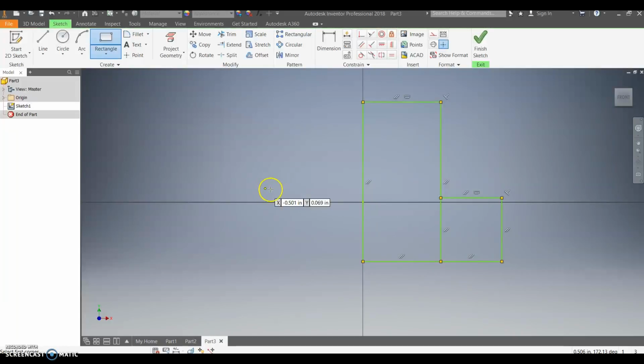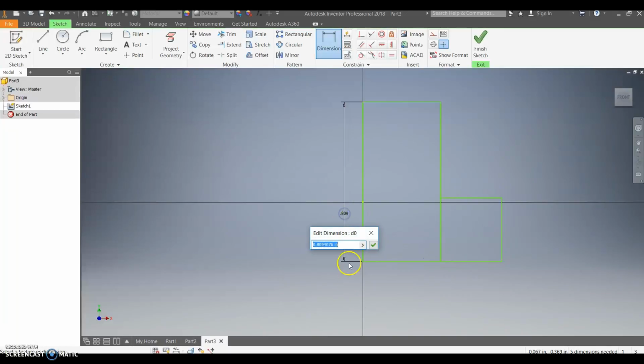One thing I'm going to do first, though, is I know that these are two different drawings. And if I add dimensions, like this, and I want to go and trim this later, alright, I can do so. This dimension's not right, obviously. So we're going to change this. The trim tool was highlighted. When a tool is highlighted, I cannot click on a dimension line. I actually have to hit escape and get out of this highlighted box. And I can go back and edit this dimension just by clicking on it.